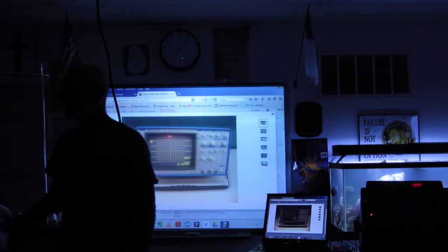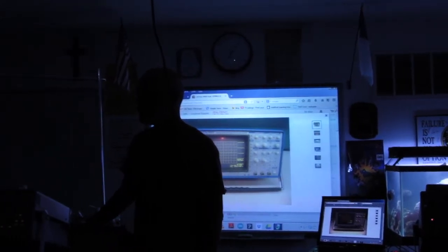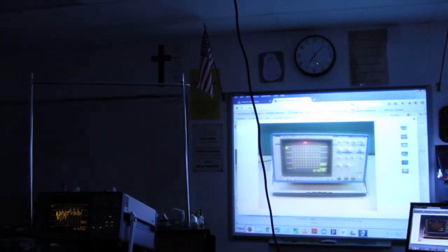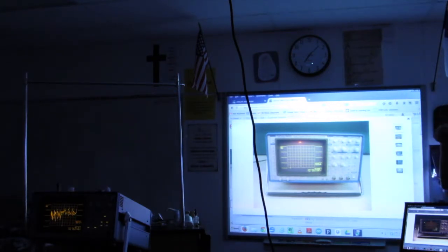Okay, Sam? It's a really random question, but can you switch the x-axis and the y-axis so it's coming down the screen? You can't, but you can go into a mode called XY mode, using the external input on the horizontal channel. The horizontal channel disconnects from the oscillator and connects directly to the external input, and will modulate the sweep according to that X input. The vertical channel still modulates the sweep on the vertical axis.